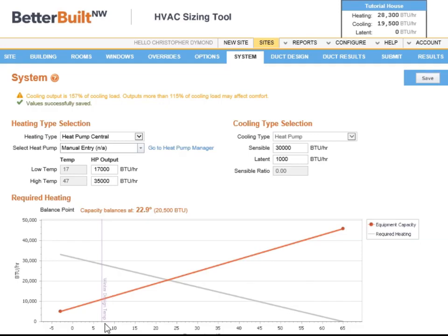That's right. If we sized traditional heat pumps down to the winter design temperature, the system would be so oversized for 80% or 90% of the time. It'd be way oversized in cooling mode also. That's why we have to be very careful about designing our auxiliary heat to meet those few days of the year that it's actually below 23 degrees.